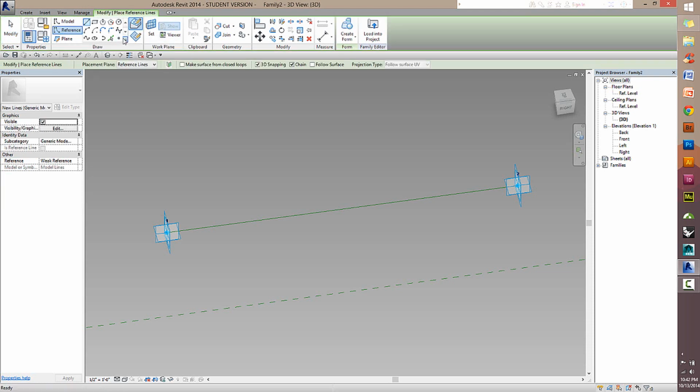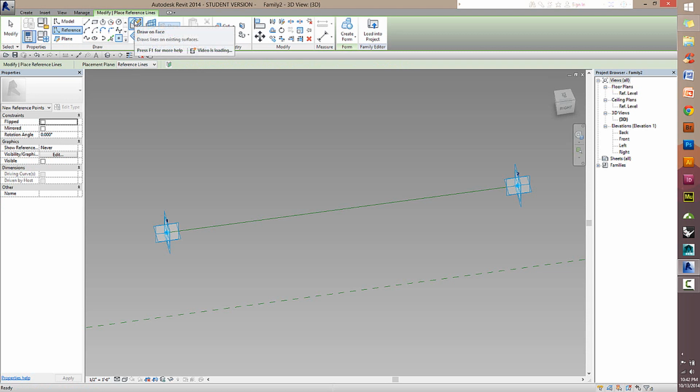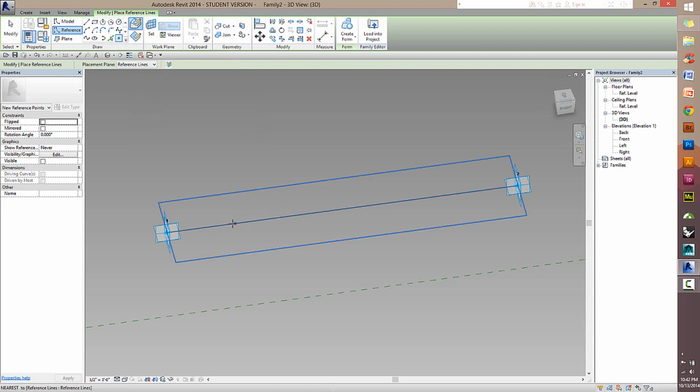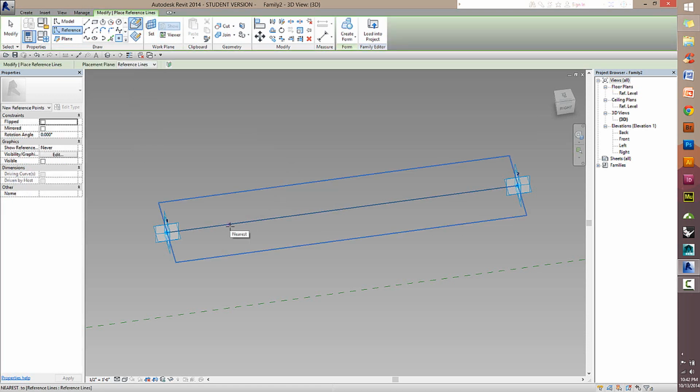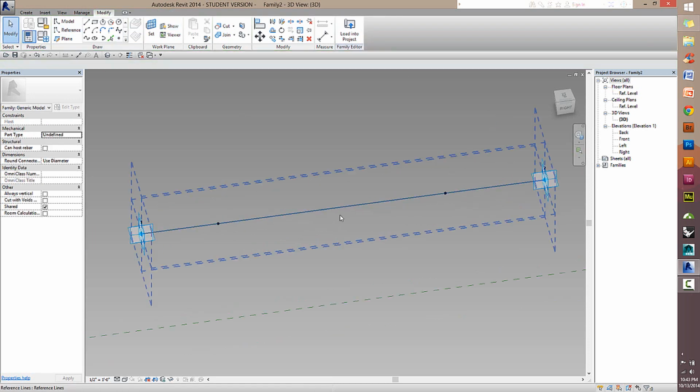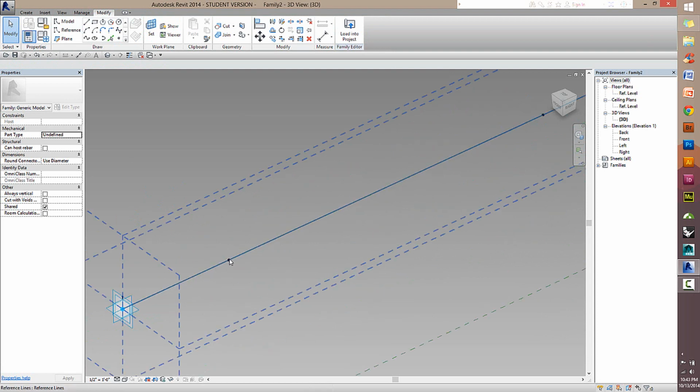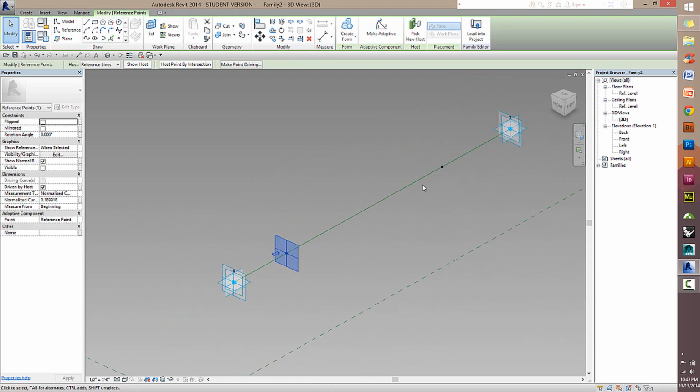So what I'm going to do to create said geometry is go back up here, create a reference line, point. It's going to be associated with a face, and then I'm going to set the work plane to this. It doesn't matter that much, but it might matter if you had the wrong work plane selected. Then I'm going to place 2 arbitrary points along this line.